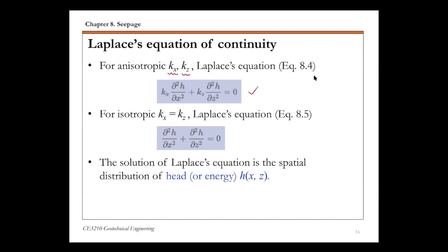And if Kx equals Kz, if it's an isotropic material, then the Laplace equation boils down to this simple expression here. And if you look at this second equation, you will notice that this Laplace equation is actually independent of hydraulic conductivity. So the solution of this Laplace equation for isotropic media is independent of the hydraulic conductivity. It depends on the geometry of the problem, basically.